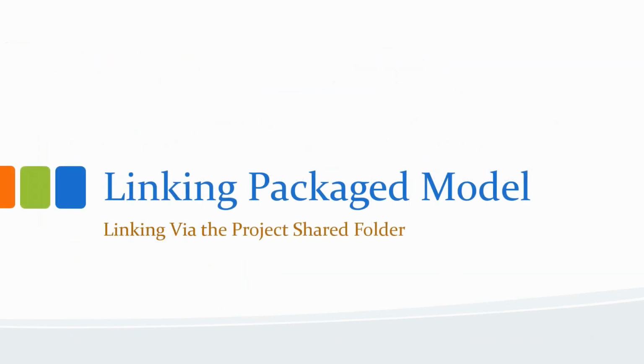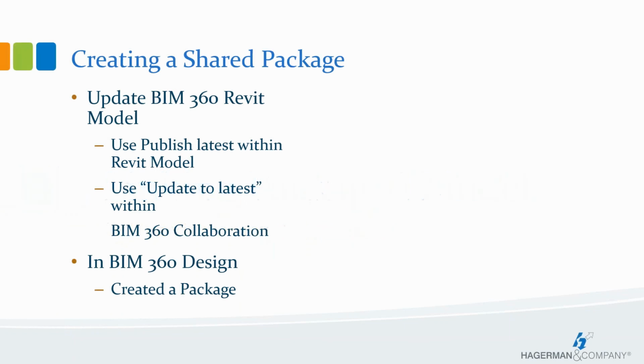So let's take a look at linking a packaged model. So as the model host, you may only want to share the model with other teams after major changes or a designated benchmark. If you're linking in another team's file, you may not need or want to see every change that's happening within the linked model throughout the design process. This is one of the benefits of linking to a shared package model.